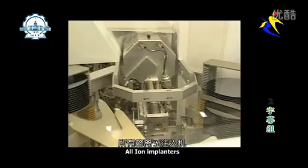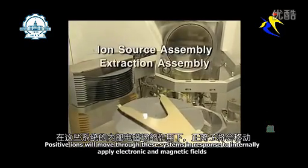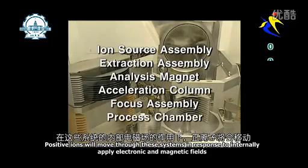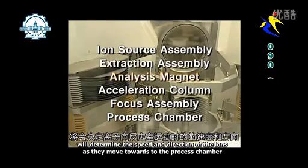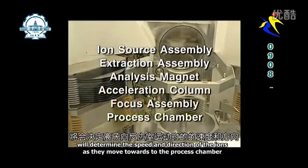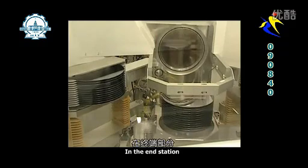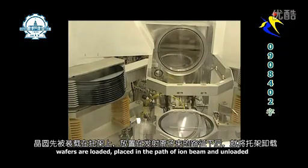All ion implanters have basic subsystems in their beamline. Positive ions will move through these systems in response to internally applied electric and magnetic fields. Magnitude and polarity of these fields will determine the speed and direction of the ions as they move towards the process chamber. In the end station, wafers are loaded, placed in the path of the ion beam, and unloaded.